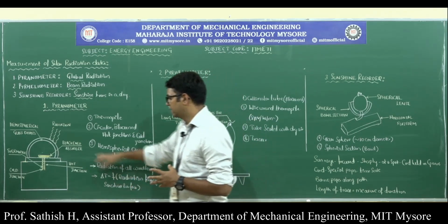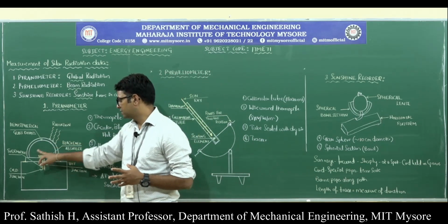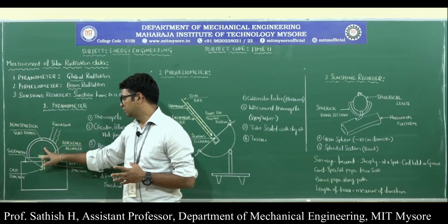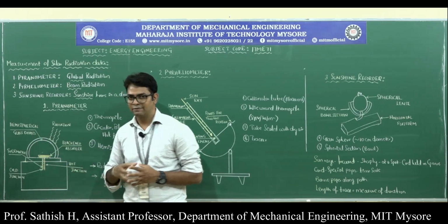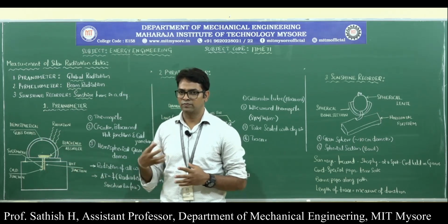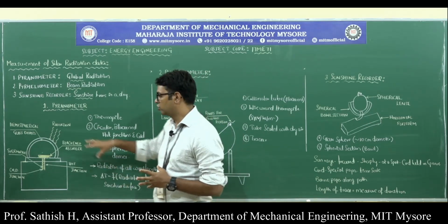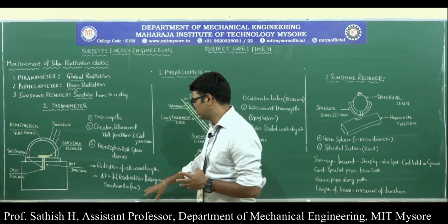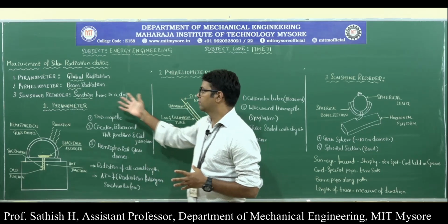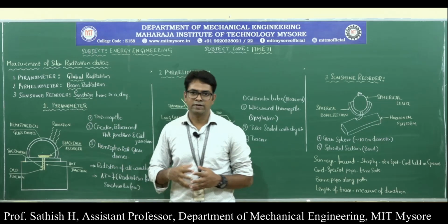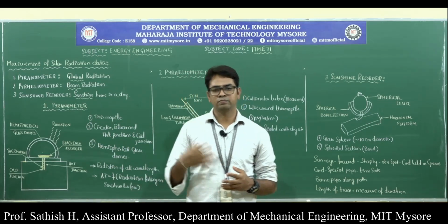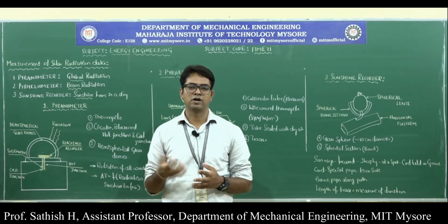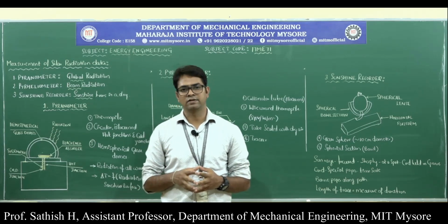sensitive surface. The radiation falls on the sensitive surfaces after passing through the hemispherical glass domes, and the difference in temperatures between cold and hot junctions gives you this function of radiation falling on the sensitive surfaces. So this is about a pyranometer. Using this pyranometer we measure global radiation on horizontal as well as inclined surfaces.